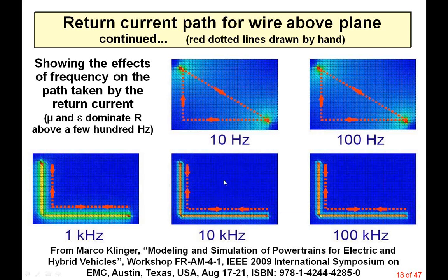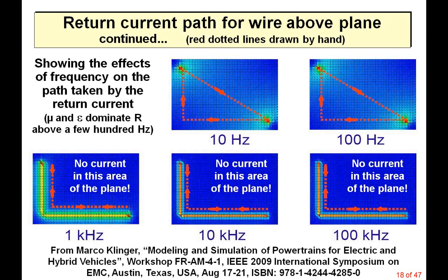Actually it has a very tiny current flowing in it, but again that's something for another day. So there's a strong current underneath the wire and none anywhere else. You may find this surprising, but it's a simple test you can do yourself with a bent bit of wire, a metal plate, and a close-field probe.